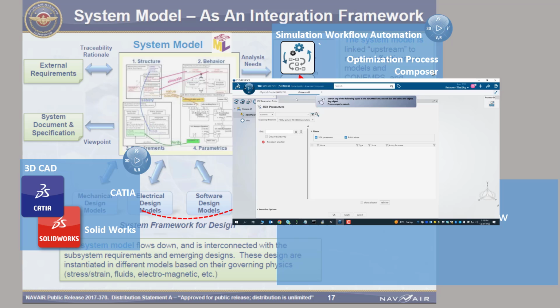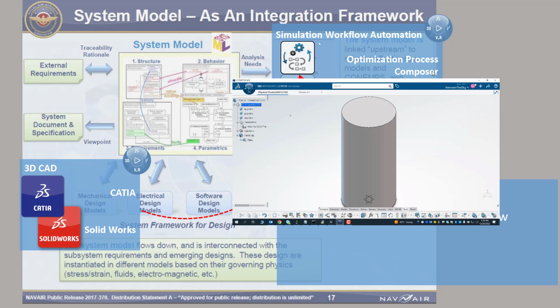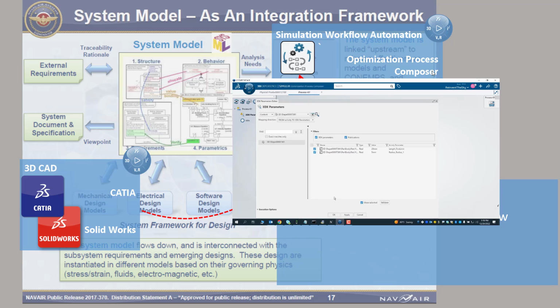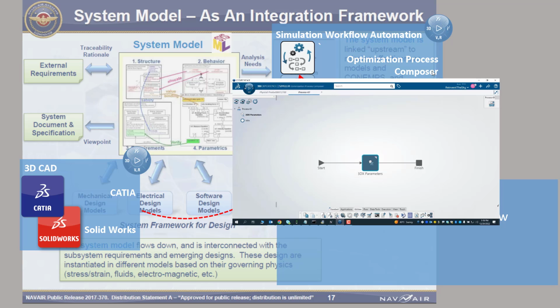As you can see here, we take the same 3D CAD which we created, and we drag and drop it to enable parameterized access to the 3D CAD in order to change those parameters later from the system architecture and get results. So in our case, we are changing the characteristics of the shape and we get the volume out of the box, right?